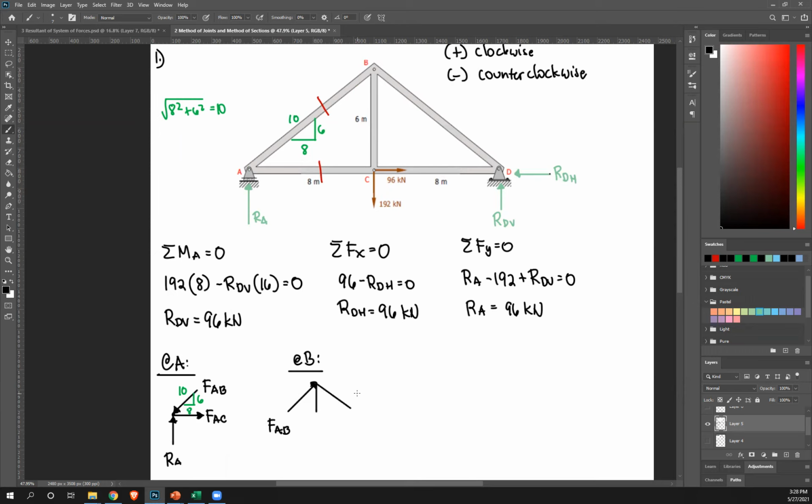Next, we also have other forces. So FAB, next FBD. Make an intelligent guess to get its direction. This is upwards to the right. I need a force to the left to counter that, and I can get a force to the left from FBD. Therefore, I'll choose this as the direction so that it's to the left. Both of my forces are upward, therefore I need a force downward. So I'm going to take it from here, your force BC.